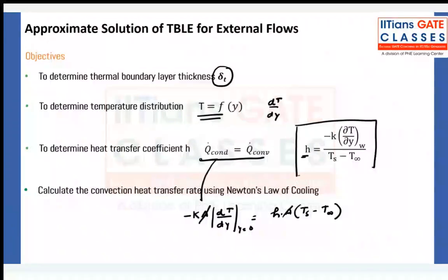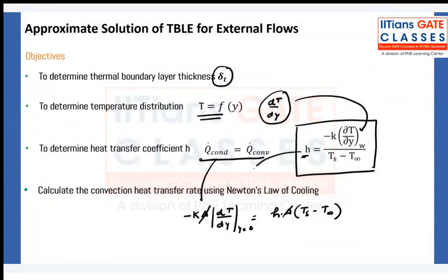So what will I do? I will calculate this. This is my second objective. Then I will put this here and calculate h. Then I will put it in Newton's law of cooling, hA times Ts minus T infinity, and I can calculate my heat transfer. Okay, chalo.